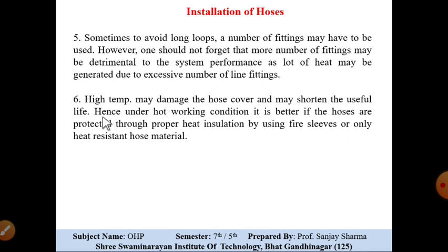So it is also mandatory to use heat resistant hose material recommended by the manufacturers, or to use fire sleeves in order to dissipate the heat and reduce the temperature.